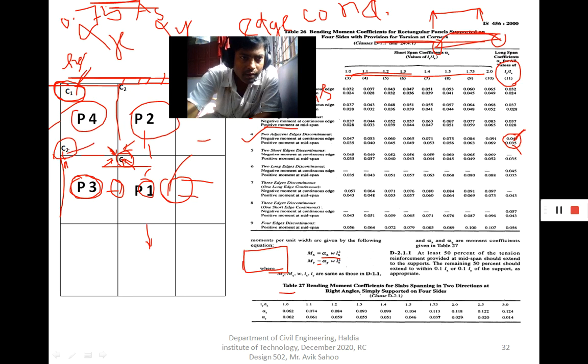The torsional force is acting like this. If I resolve these forces into horizontal and vertical components, you see that this vertical component and these panels' vertical components balance each other. So that's why in corner C2, 50% reinforcement is required, whereas in C3 all the torsional forces